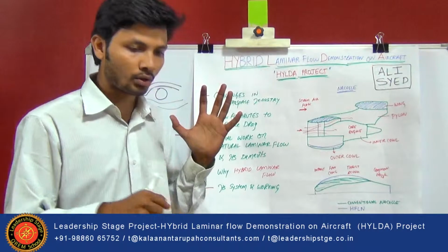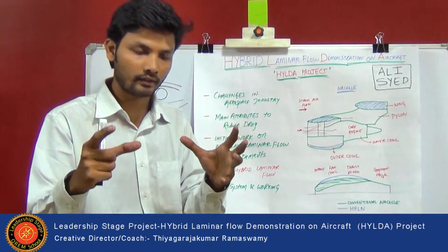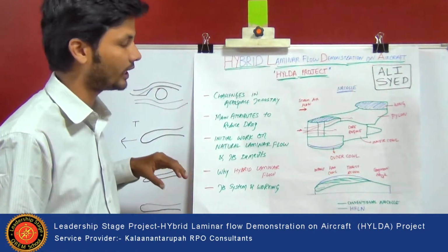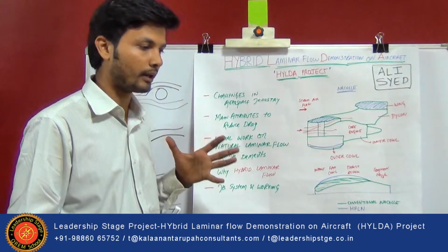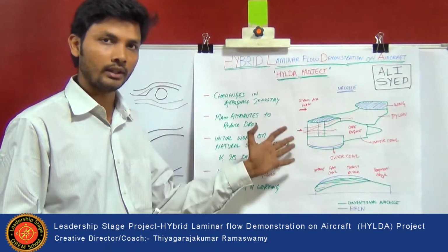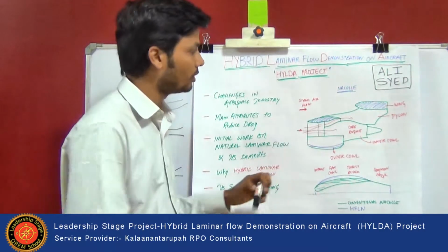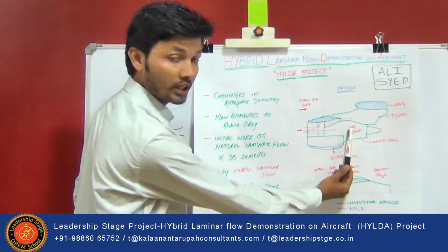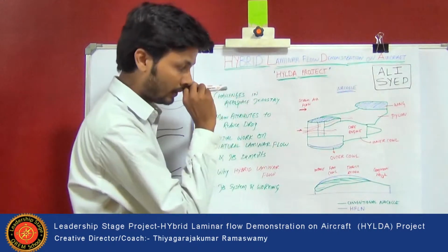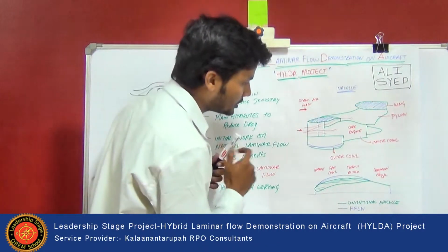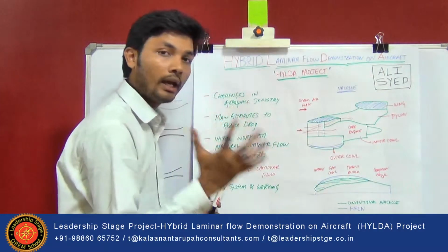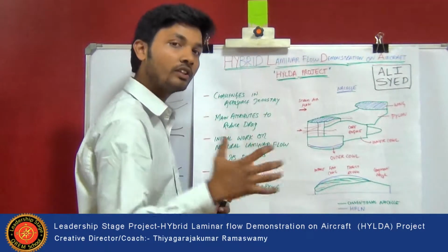So now we'll discuss what hybrid laminar flow is, what exactly we are going to do in it, and its working. The whole process of the hybrid laminar flow that I am going to explain is taken from a research paper, a United States patent by Daniel J. and David. Before going with that, we'll see the changes we are making in the hybrid laminar flow design. This is the nozzle design, this is the wing, this is the pylon, this is the core engine, and the inner core and the outer core. This is a streamline flow cutting the nozzle, and this is the intake airflow. The main changes are in the design of the outer surface and the inner surface of the inlet cowl and the fan cowls. We'll see what changes we are making.